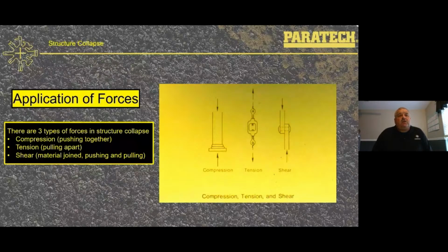The struts are actually in compression, but the braces are more in compression and tension. Shear, the shear force is there when you've got a pre-stressed floor or a pre-tension floor where the cables or the bars are compromised in shear, and thus the floor pancake collapses. We use shear when we build rakers, and when we do a lot of structural collapse, it's in the picket system. The picket system will have a tendency to have the shear force application.